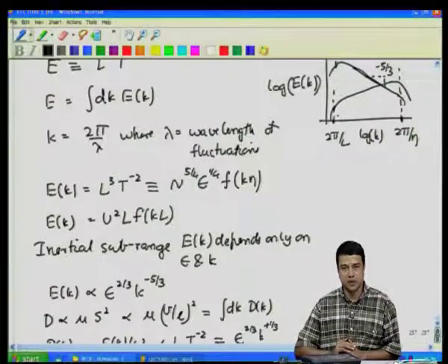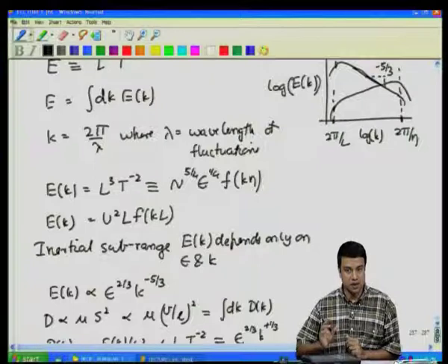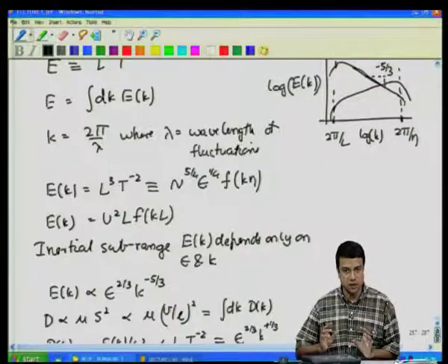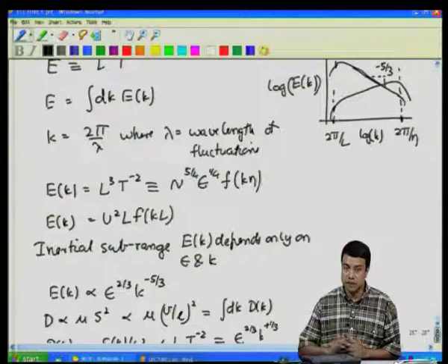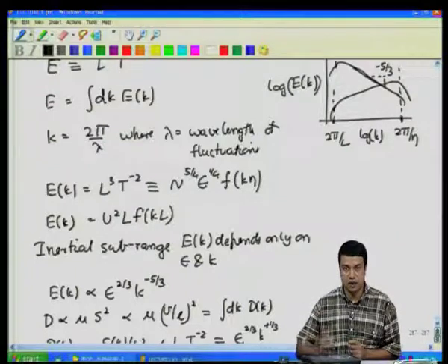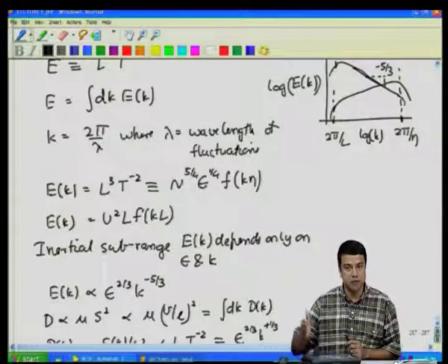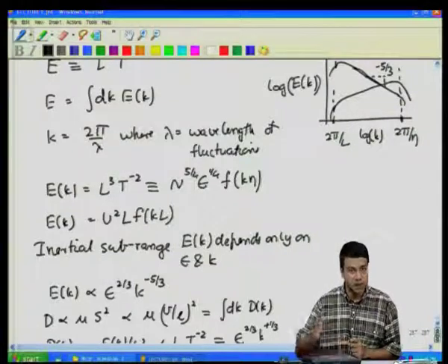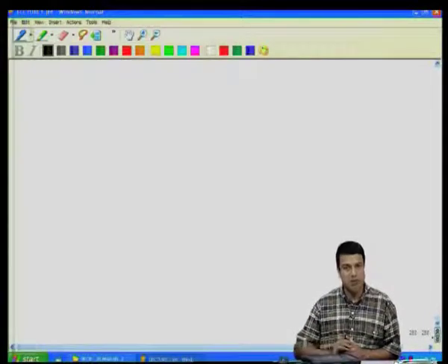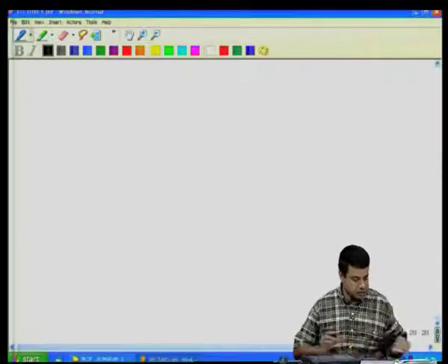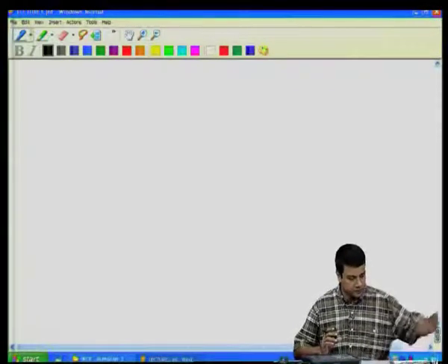in the intermediate range. So what this states is that the energy in the mean flow is much larger than the energy in the smallest scales, whereas the rate of dissipation of energy is largest for the smallest scales. K is equal to 2 pi by eta corresponds to the smallest scales of the flow, and the rate of dissipation of energy is largest for the smallest scales. So this gives us a comprehensive idea of the flow energy, the length scales and the dissipation scales in